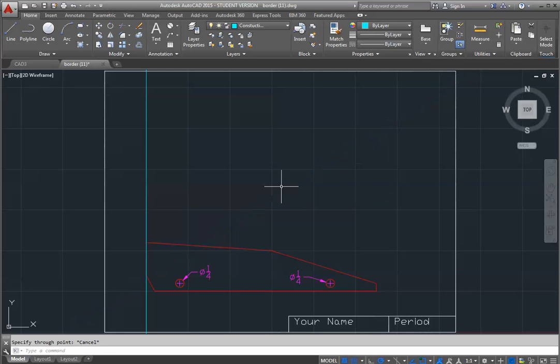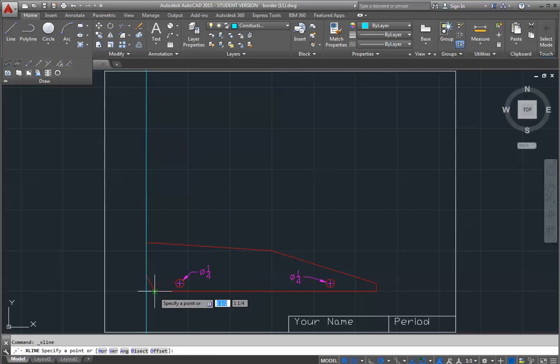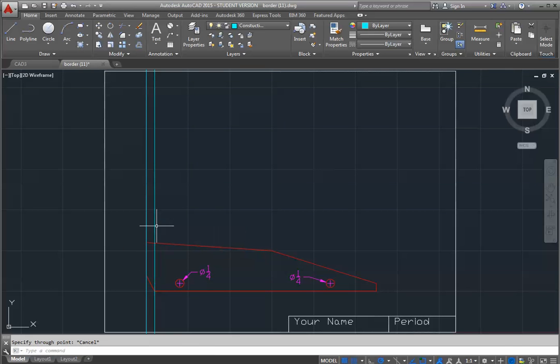Okay, that's why they call this orthographic projection. Whoops, I've got to use the construction lines. So I'm putting the line there. Be thinking about what kind of line I'm going to see. I'm going to turn this object on its side, looking down at the top, and I've got to determine whether it's an object line, a hidden line, or a center line. So be thinking about what we would put. So I'm going to put a construction line here.